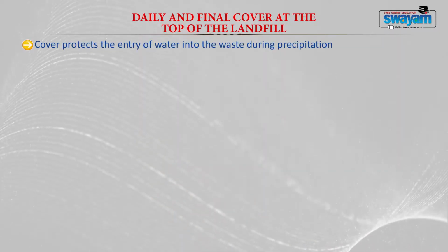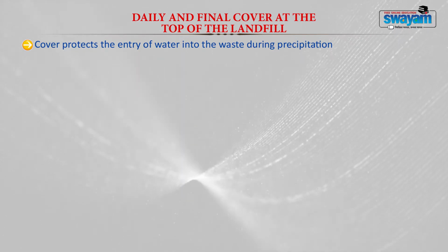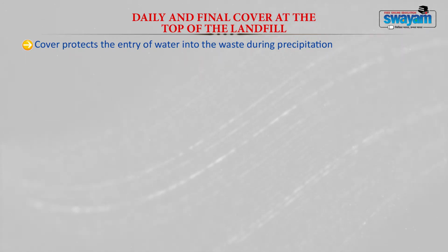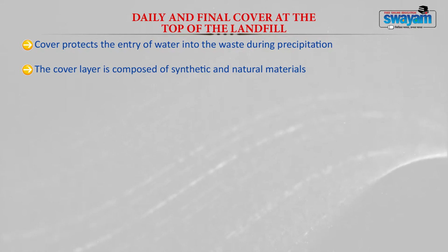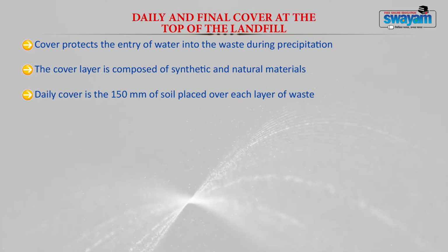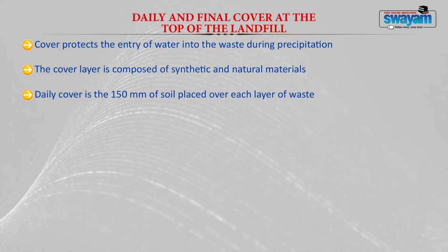Now, the next component is your daily and final cover. Similar to a landfill process, after you load the waste, it should be covered with a cover material, and after every day of loading you should also cover it with a cover material. Cover generally protects against the entry of water into the waste during rainfall or any other form of precipitation, and it also keeps animals away from the waste material. Generally the cover layer is composed of synthetic and natural materials, and this cover layer extends to a level of 150 mm of soil which is placed over each layer of waste and at the end also.